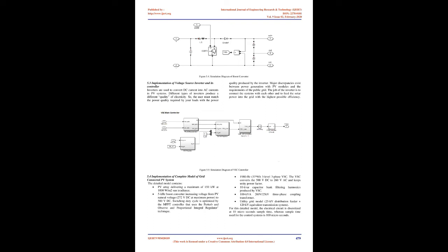3.1.4 Constant voltage method. This method, which is not so widely used because of the losses during operation, is dependent on the relation between the open circuit voltage and the maximum power point voltage. The ratio of these two voltages is generally constant for a solar cell, roughly around 0.76. Thus the open circuit voltage is obtained experimentally and the operating voltage is adjusted to 76% of this value.